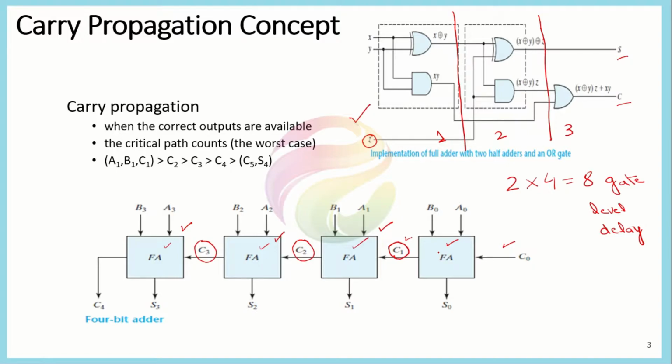In today's world, we require a faster system, and this system you can see is quite slow, because it has to wait about 8 to 9 gate level delays. So there should be some mechanism so we can reduce this computation time, and we need to now view some other mechanism to minimize this whole time, because till now what we have done is that we have used K maps and other Boolean algebra to minimize this circuit. Now we are moving to another concept for maximizing the speed of the circuit.